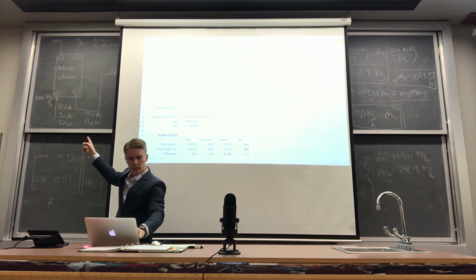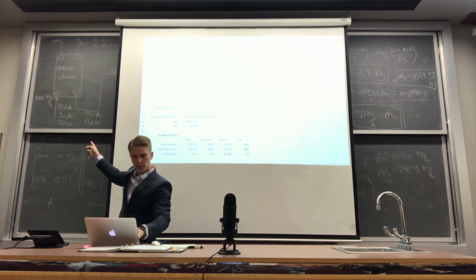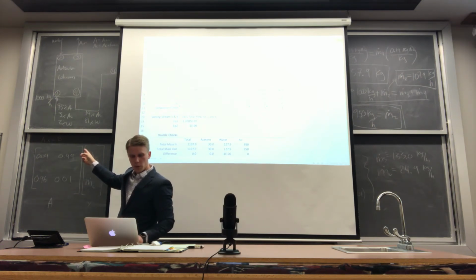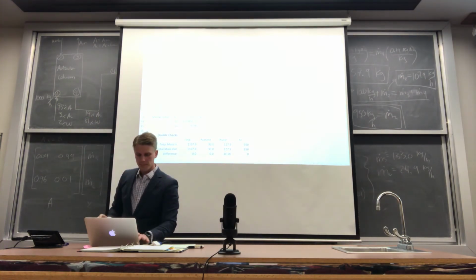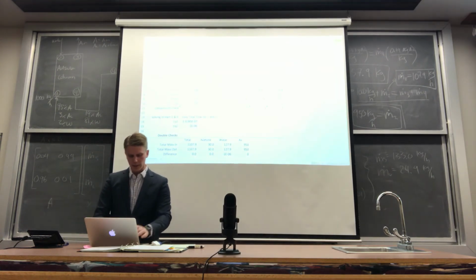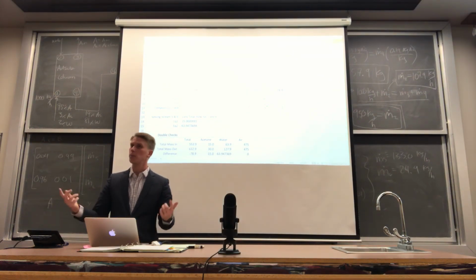It's the in, so I have in minus out. So I solved for stream 2, but if you were to work out D7, E7, and B7, it corresponds to the total flow rate of 1, 3, and 4. And so you can see that I just typed that into there. And so if I change my basis to like 500, right, everything should automatically update except for these two columns right here, right, because these are input cells.